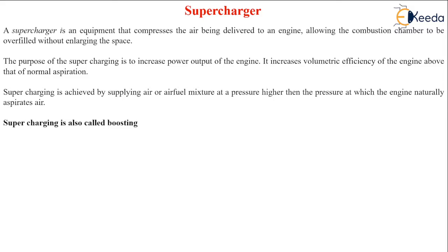However, in case of a CI engine, if the pressure and temperature of the air which is coming inside the combustion chamber is on the higher side, then this will ultimately result in a shorter ignition delay, which in turn will lead to a reduced possibility of detonation and knocking.